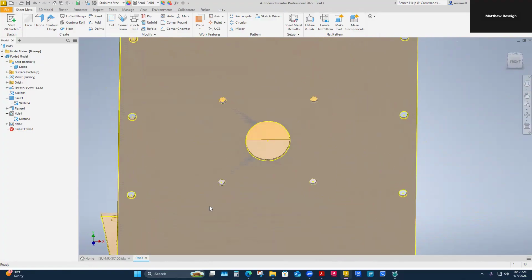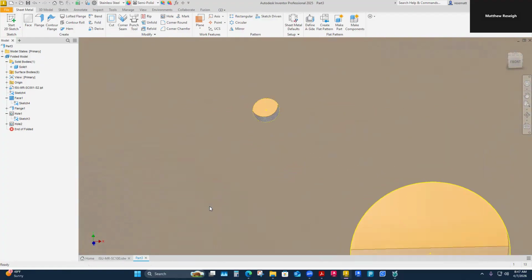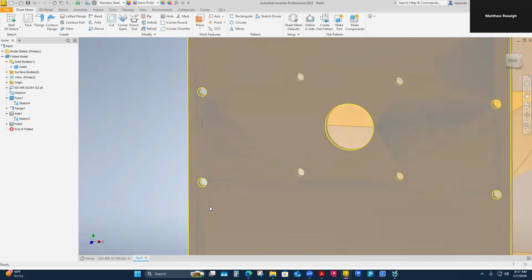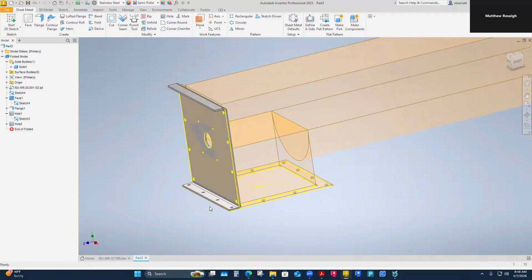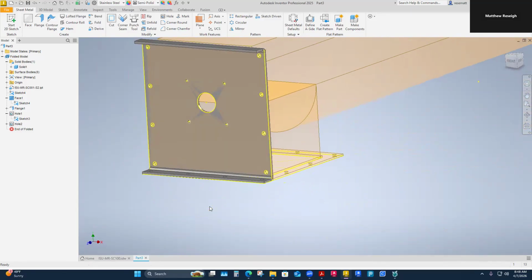Was it construction? Yeah, when I projected them, I changed them to construction because I didn't want to have to... It wouldn't be the end of the world if you did. You would just have to go through and select those profiles to make solid with the original face solid. Because I don't want them to be just through, I need them to have threads in them. And yeah, technically by making them construction, they didn't even select for me.